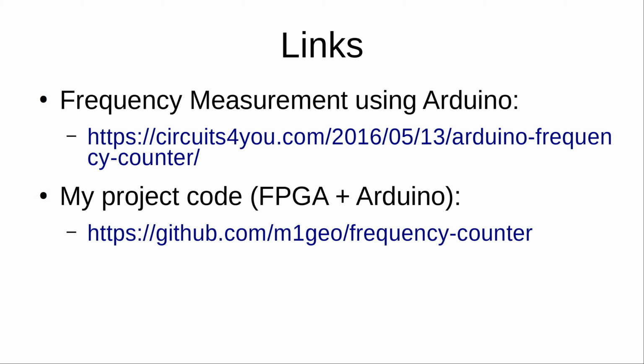You can also use it with a 1 pulse per second from a GPS and make quite a good frequency counter. And with that FPGA, you're able to count well over 500 megahertz with a 1 pulse per second from the GPS, and it works pretty well. And that was the reason for the other GPS on the dev board originally.